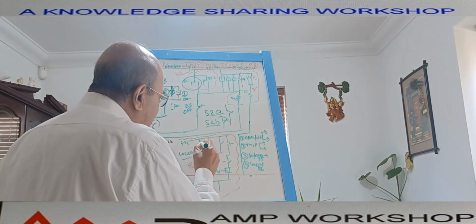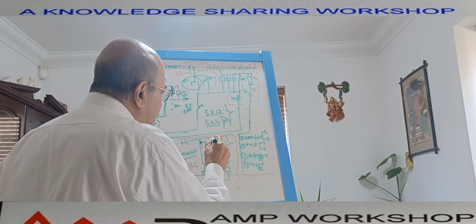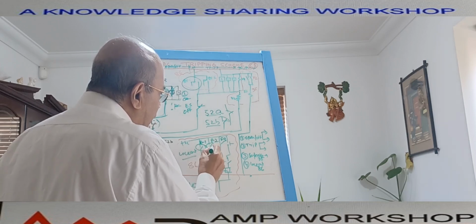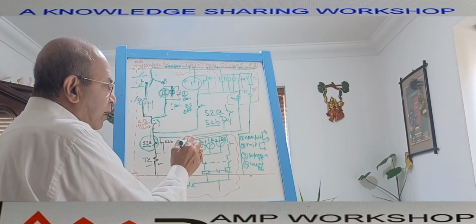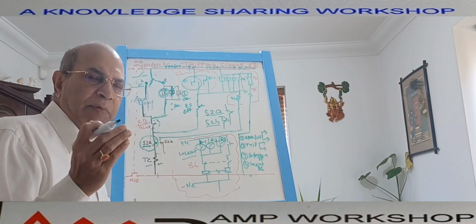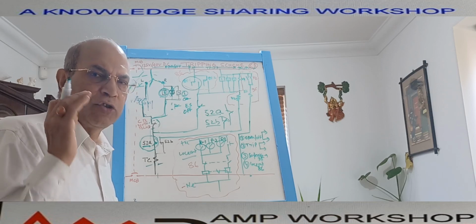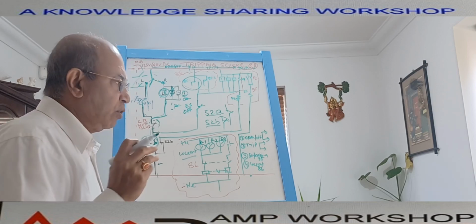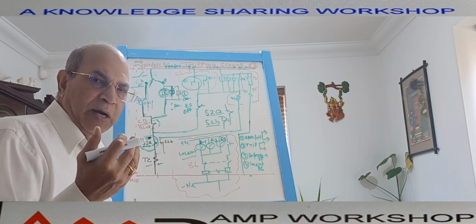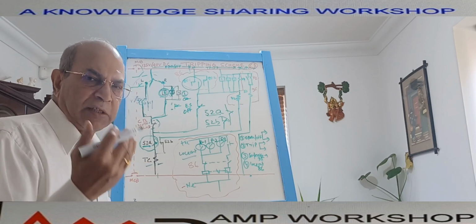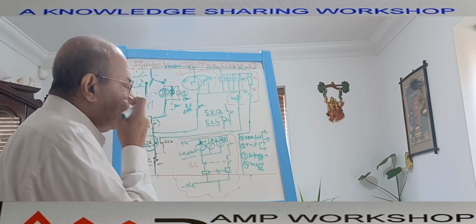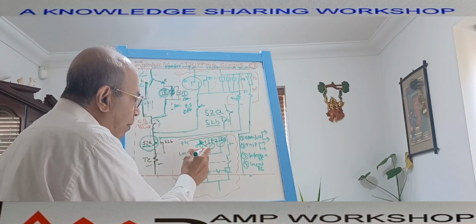These are the various protection functions. Suppose this is P1, P2, P3, the output contacts of the digital relay. Suppose P1 output of the digital relay is configured for the phase overcurrent fault. The moment a phase overcurrent takes place, by sensing the CT supply, the digital relay understands there is a phase fault. Immediately this protection function inside the digital relay, or the output relay, will operate.